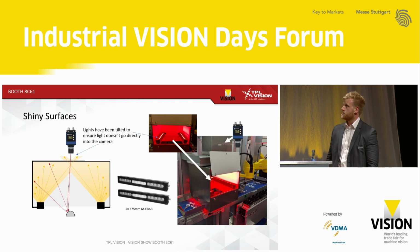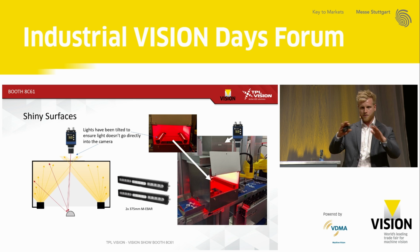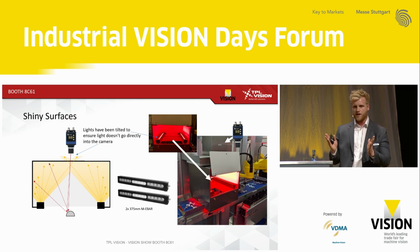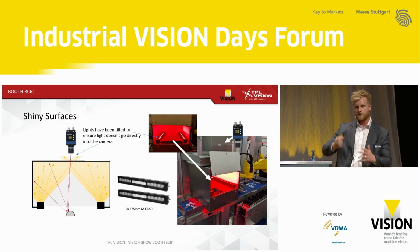We often give the guidance that it's best that the customers try and point the bar lights away from the camera. If you're using powerful direct bar lights, you want to avoid direct emission into the camera. So you just need to do some maths to figure out the size of the box and the direction the light should be facing to illuminate as much of the surface as possible inside the dome, and then make sure that the camera is spaced far enough back from the dome so that it doesn't capture any of the direct illumination.